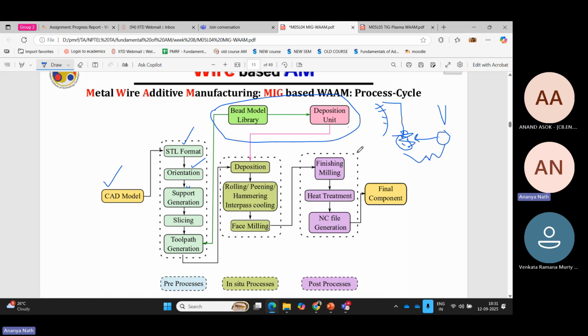That's why, in case of stainless steel, we get some martensitic formation, some brittle phase formation, because of which additive manufacturing is mostly followed by heat treatment to relieve the residual stress and dissolve these hard phases. That means it is done during post processing. In this process also, we are doing the milling. As soon as it cools down, and it will cool down very easily, we can start the milling process. There will be no harm.